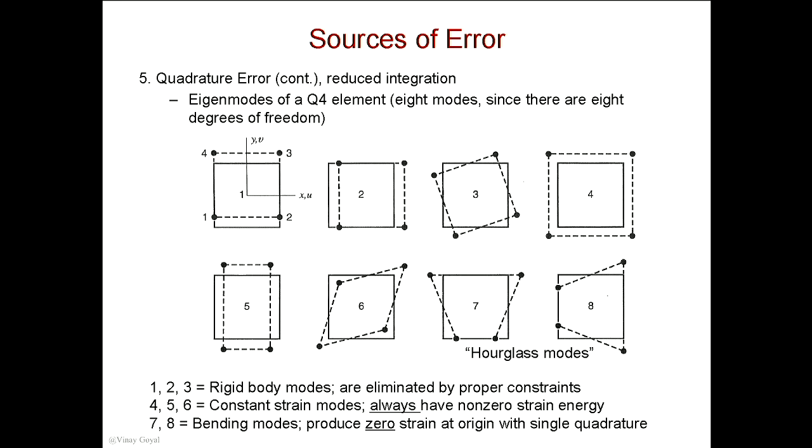But now let's look at a single integration point, reduced integration for a bilinear element. So if I'm an integration point down here, a little ant in the middle of this quadrilateral, and I look that way, and that way, and that way, and that way, do I see this moving outwards? I do, because I know I was here. This point can actually see that I was here and I moved there. I can see I'm expanding. This element is expanding or contracting.